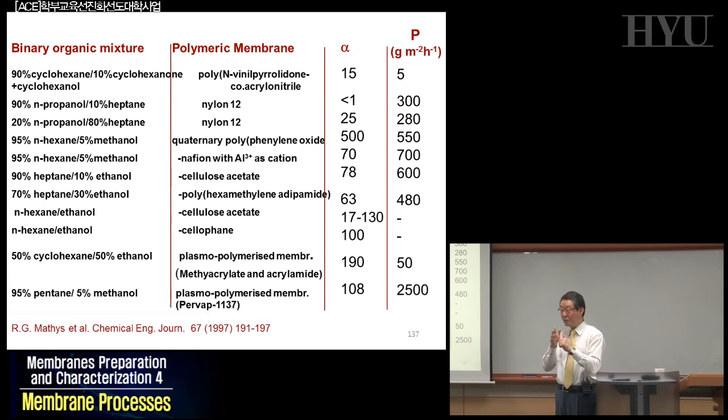components such as methanol, the benzene. Okay, if you add a small amount of benzene, then you break the azeotropic point, and then you can continue on the distillation of the ethanol and the water, coming up to about 99.9% of the ethanol. So you see, if you buy your chemical ethanol, 95% ethanol is very cheap.